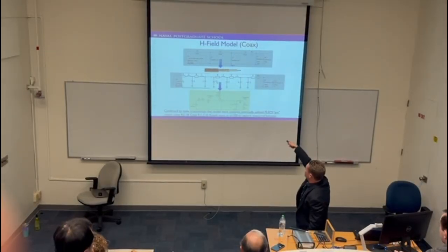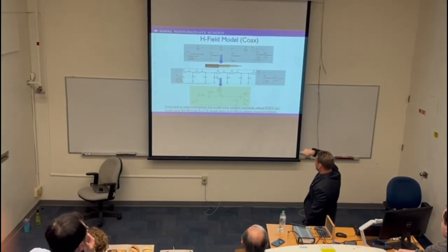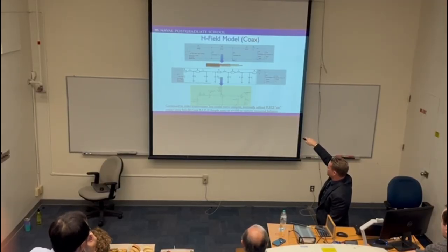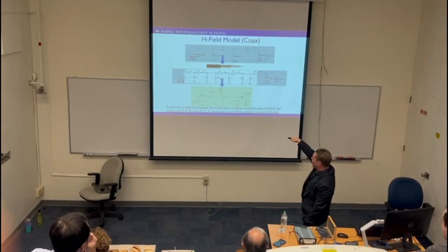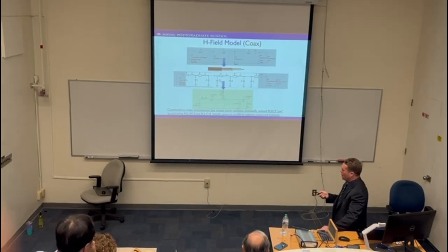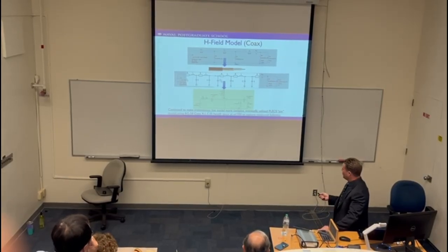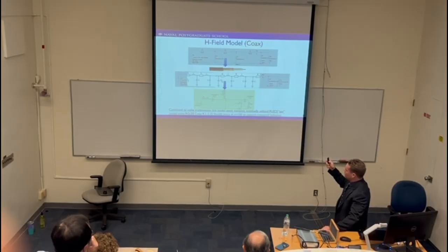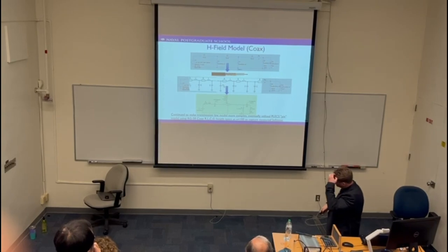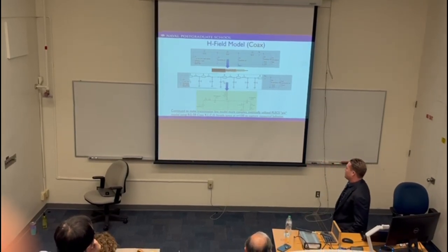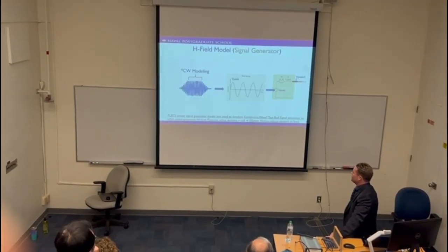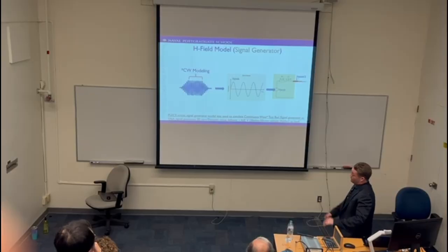I started advancing, started moving along here. I ran a pi type circuit through a couple of them and improved the accuracy a bit, but not until I went to a pi type of about 100 was I finally able to see and overlap the exact coaxial behavior I was seeing, with resonant frequencies, resonant impedances, and everything. Once I got all that to completely overlap, I knew my coax was finally sufficient. We had to look at the specs of an RG58, the resistance per length, inductance per length, capacitance per length, and cascade over 100 of these together to finally capture some of the standing wave behavior that was there. So that takes care of the coax portion.